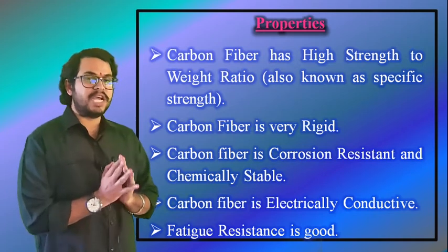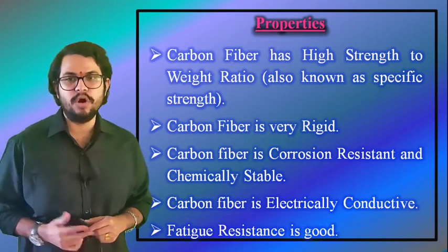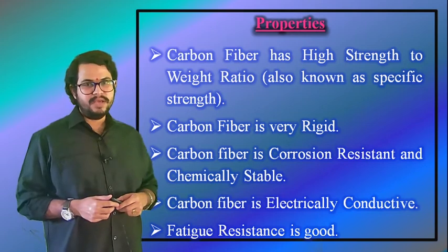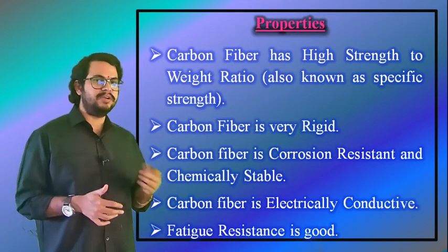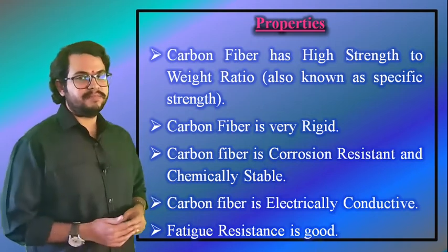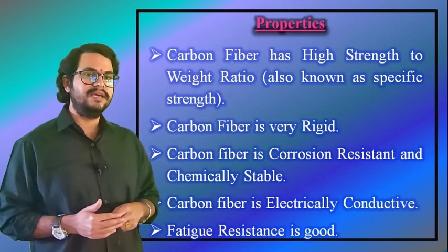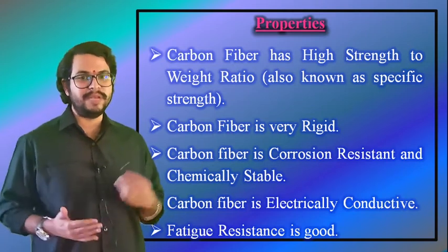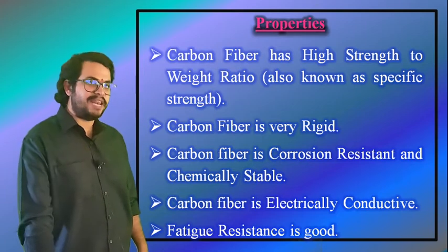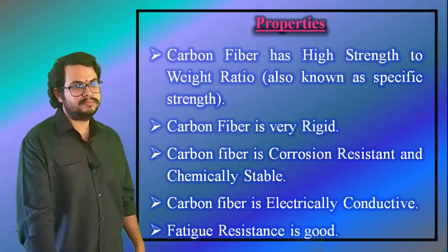Okay, carbon fiber is corrosion resistant and chemically stable. Although carbon fibers themselves do not deteriorate, epoxy is sensitive to sunlight and needs to be protected. The other matrices, wherever the carbon fiber is embedded, might also be reactive. It is electrically conductive, right? And this feature can be useful and also sometimes a nuisance. If boat building has taken it into account, just as aluminium conductivity comes into play. Okay, the carbon fiber conductivity can facilitate galvanic corrosion in fittings. Careful installation can reduce the problem.